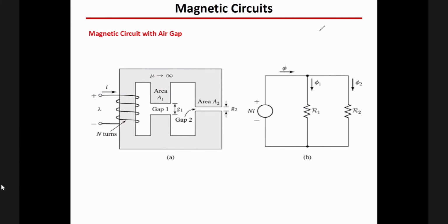If a magnetic material gives you high permeability and low magnetic losses, and reluctance is almost zero, but it is expensive, you don't use it for certain applications. You choose a material that is cheap and will give you reasonable reluctance. So you cannot assume that the reluctance is always zero and mu is infinity, or large enough to be assumed infinity.